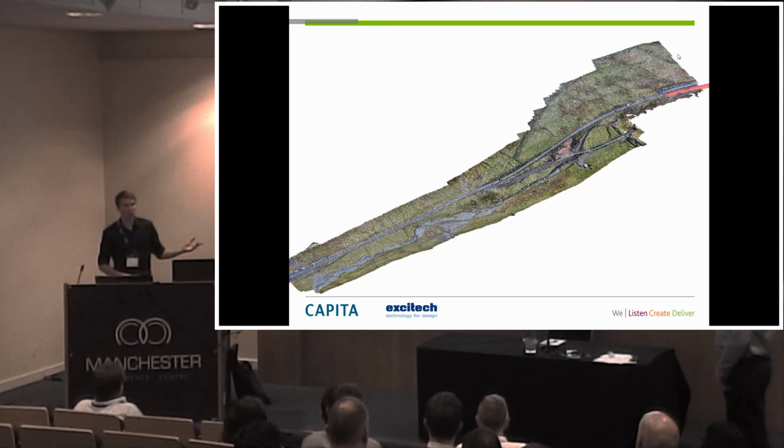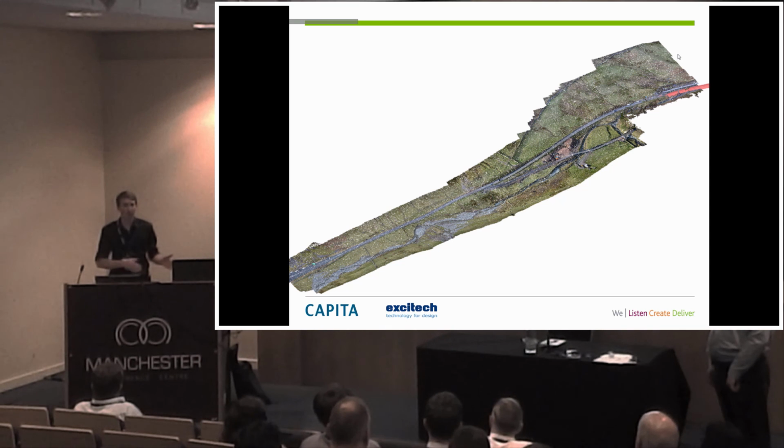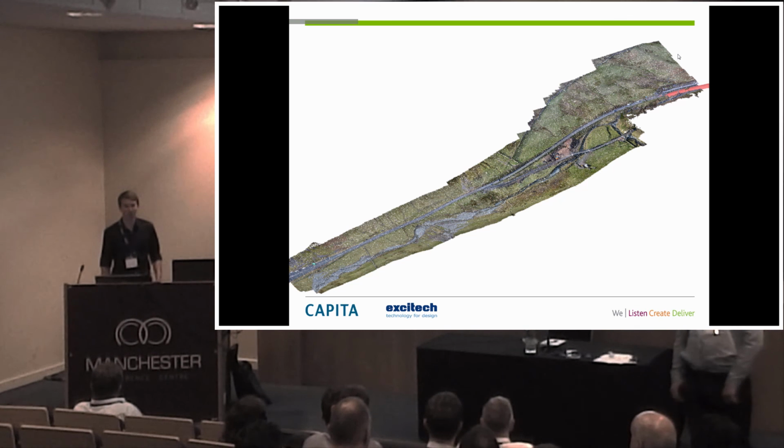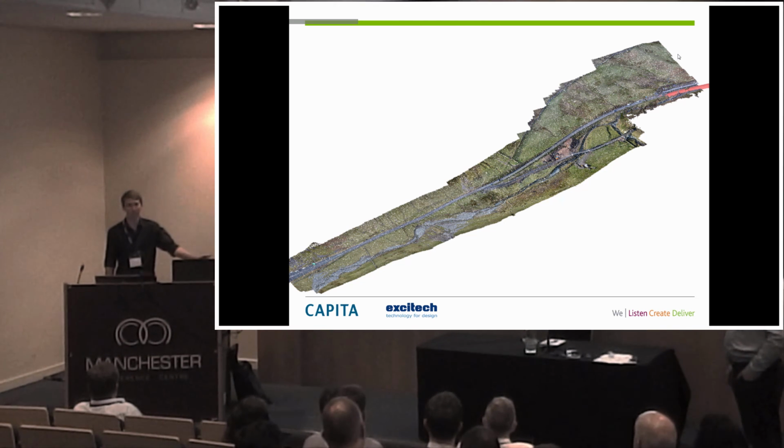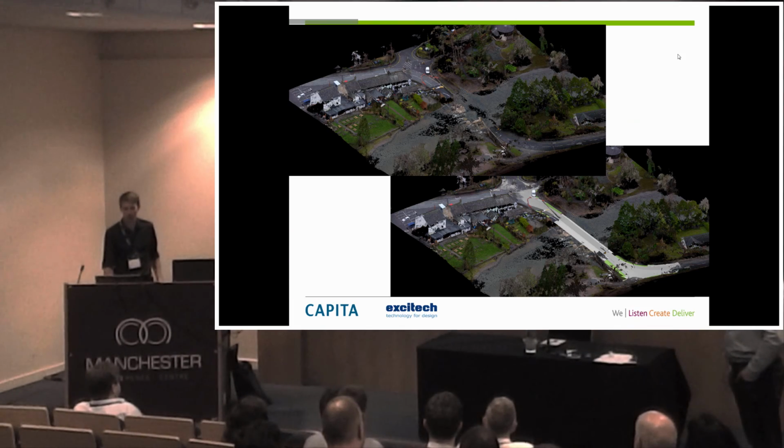However, the accuracy in this one isn't as good. For the tower, we said it was plus or minus 5, 10, 15 millimeters. This one might be plus or minus 20, 30, 40 millimeters. But in terms of knowing how many cubic meters of soil we need to bring in, plus or minus a meter was really good enough for the purpose. So that comes into it when you acquire a survey: what tolerance do you need? Not just going in and saying, I need it to the closest millimeter. If you're doing work like this, you can really do it with less tolerance.